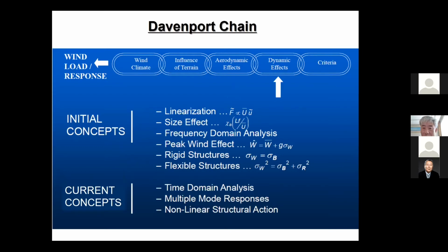Now for the dynamic effect, its initial concept considers, for instance, the size effect, linearization, and the frequency domain effect, peak wind effect, rigid structure. For rigid structure, we have this description, and for flexible structures, we have to combine the background and the resonant component. So currently, people will do more time frequency analysis and also multiple mode response and nonlinear structure actions.